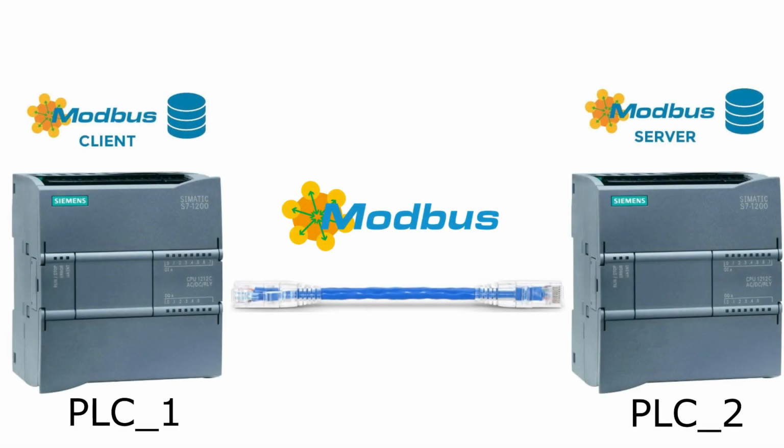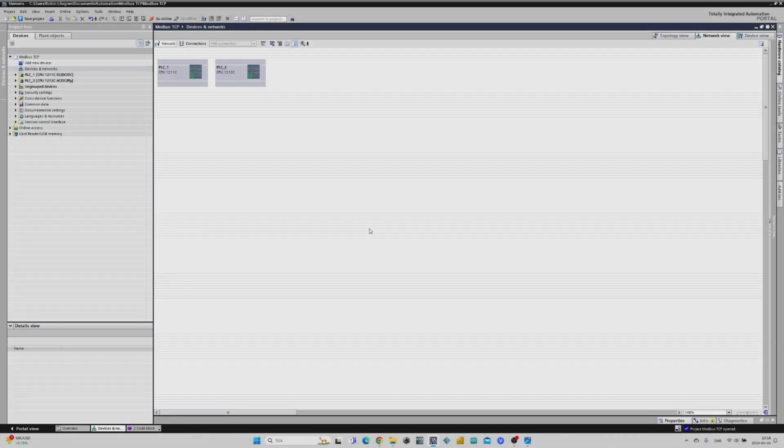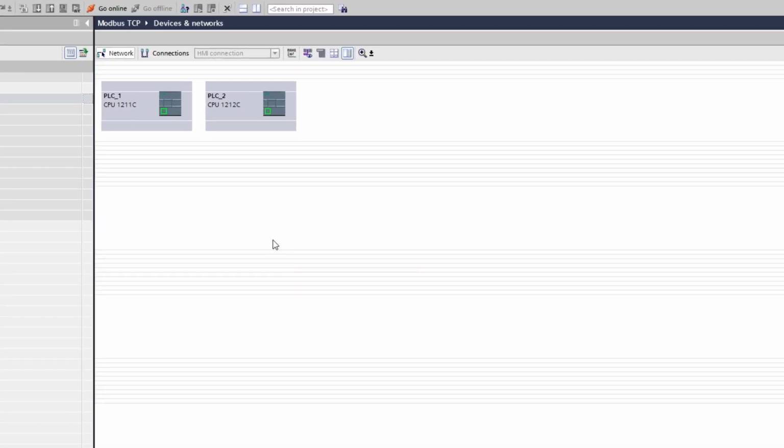In today's video we will go through how to set up a Modbus client connection between two Siemens S7-1200 PLCs using Modbus TCP/IP protocol. I have already made a project and added my two PLCs to the project. PLC 1 will be used as the client, and PLC 2 will be used as the server.